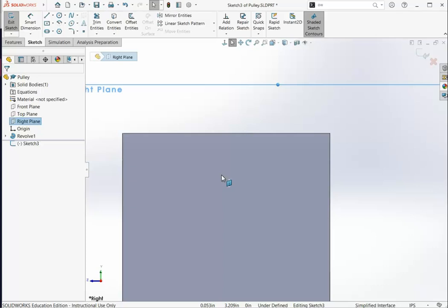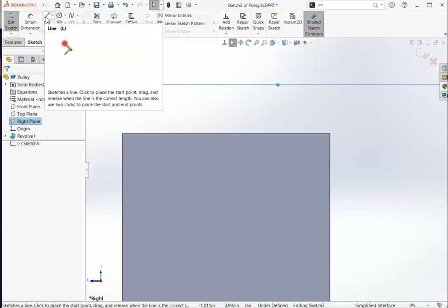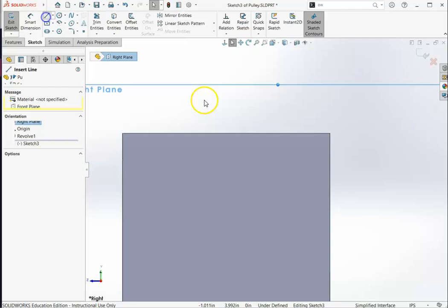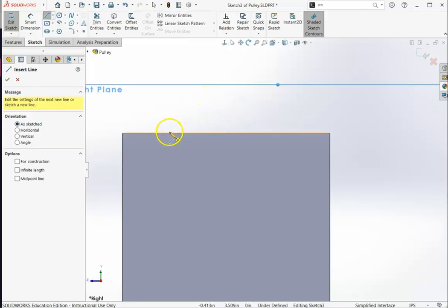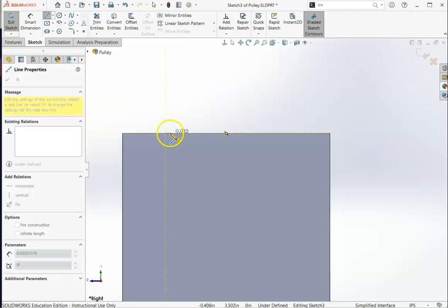on figure 176 and through probably 180, I can see the dimensions that I need to make for this little channel that I also want to revolve around my pulley. So in order to do that, they suggest that we draw the basic shape of the channel using 4 lines. So they want us to draw a line that's parallel with the top of the part, or not symmetric, but is collinear with that top edge.